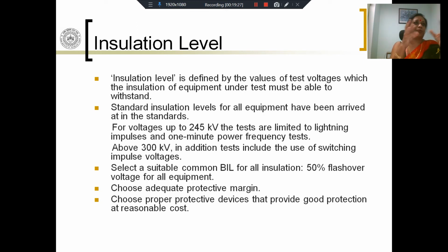When you have a power transformer, there are IEC or IEEE standards which specify the voltage level for every insulation that you provide, let's say turn-to-turn insulation or bushing insulation. Depending upon the nature of the insulation, the kind of catastrophic failure, the ambience, application, etc., you have IEC standards which specify the insulation level.